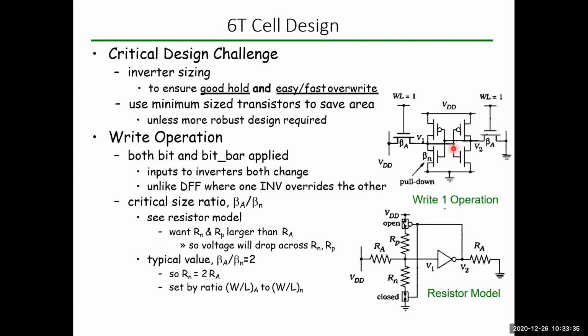And let us see the critical design. This is not much useful as a part of your B.Tech course, but anyway, it will be very helpful to understand in detail how to design a very optimized SRAM cell. In order to get an optimized SRAM cell, first you should make sure that all the transistors have the minimum W/L ratios. It means the aspect ratio should be very small.